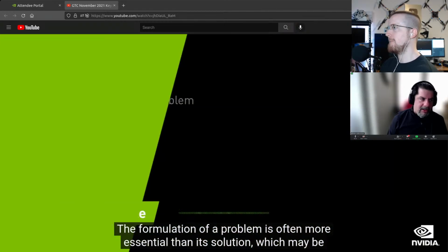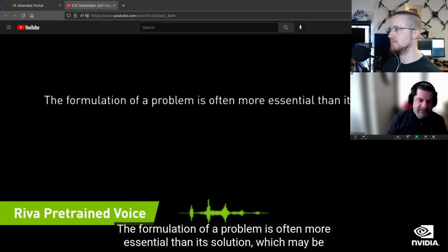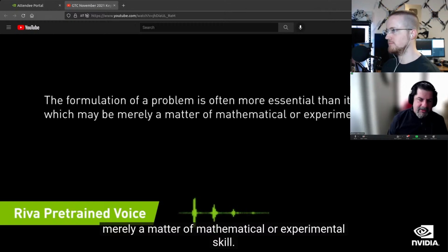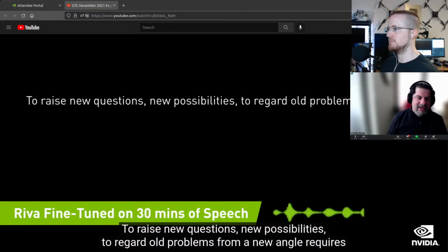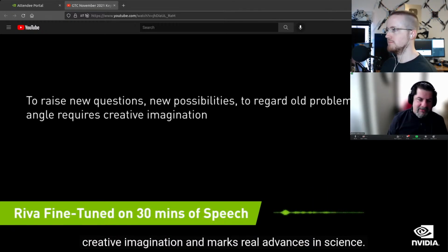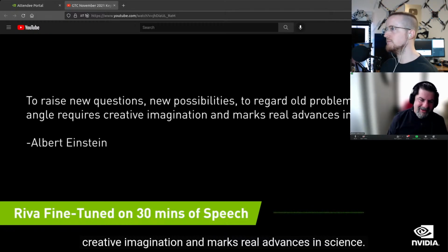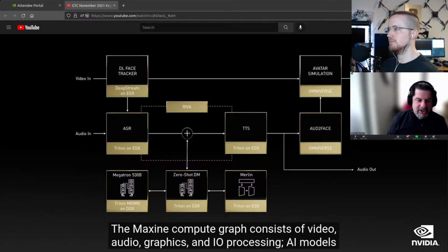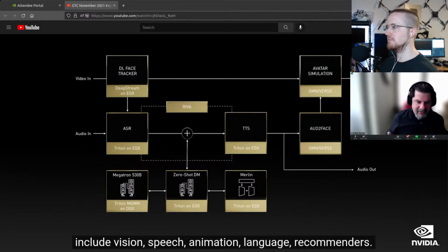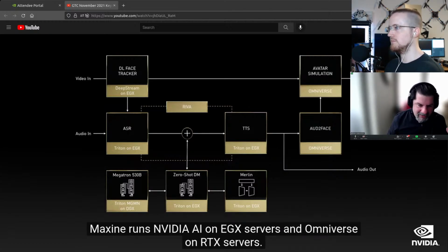So with AR, you can download a companion app for your iOS device called Omniverse Remote that allows you to connect to the computer that has the RTX card running Omniverse and have the rendering of the virtual part of your AR scene done by the bigger computer with generating the better pixels, streaming it to the iOS device, which can then composite the rendered image into the real world camera feed.